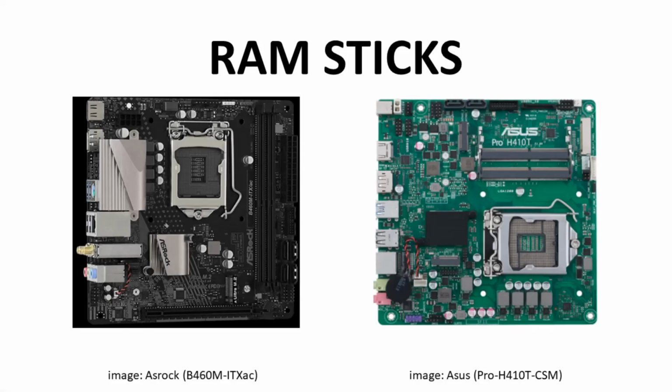An easy component to discuss is the RAM. Here are our model mini-ITX board and thin mini-ITX board side by side. From a RAM standpoint, you may have noticed that the mini-ITX board takes regular desktop RAM sticks, UDIMMs. It's kind of hard to see in this dark image, but those are regular, everyday desktop RAM slots. Mini-ITX boards go into taller cases, so having RAM sticks that stick up vertically on the motherboard is not an issue. For thin mini-ITX boards, you're restricted to laptop RAM, SO-DIMMs.